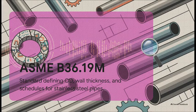So, to navigate this and find the true physical dimensions, we rely on our ultimate decoder ring, the ASME B36.19M standard. It explicitly defines outside diameters, wall thicknesses, and schedule numbers specifically for seamless and welded stainless steel pipes. If you're working with stainless grades like 304 or 316, this document is literally your engineering Bible.